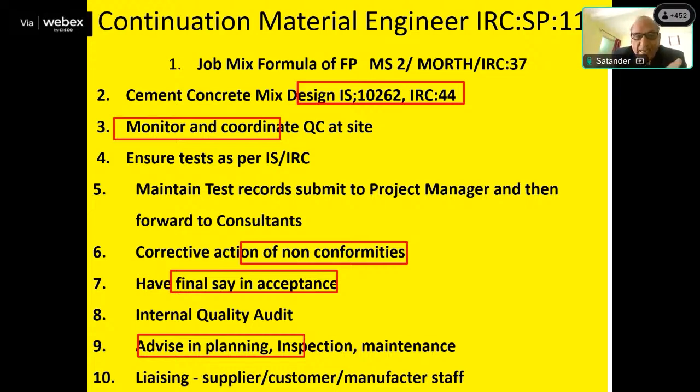Ensure, not assure, tests as per IS code. He has to see whether they are doing as per IS code or IRC code. Maintain test records. It is the duty of the material engineer to forward them to the consultant, and take corrective action on the non-conformity. Suppose the consultant gives you some non-conformity: you call him that you are going to start the pre-stressing tomorrow, and without his presence you started, then he will put a non-conformity on you. He can check the core or something else. Internal audit also he has to do, first from his side, then third party. Third party means it will not be a person from the client.